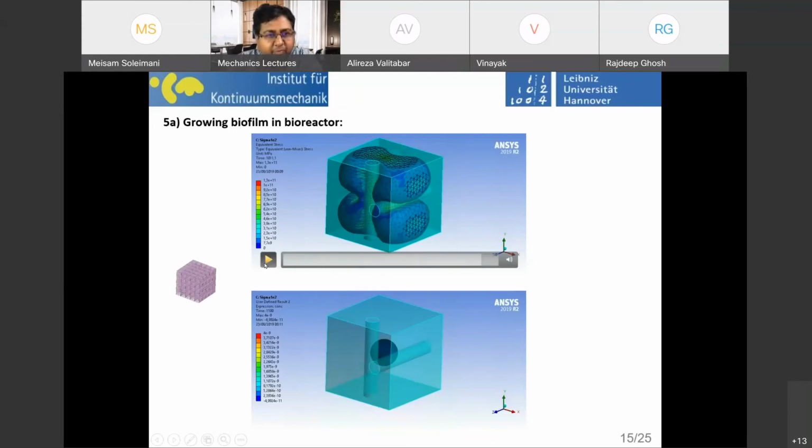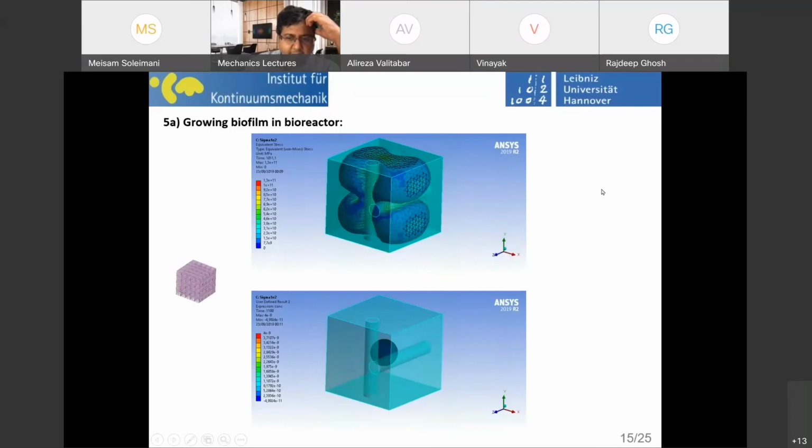If we are talking about constrained growth that intrinsically leads to compressive stresses, it is susceptible to this type of instability or buckling that has to be treated carefully. For example, in ANSYS, I had to activate in some cases line search, in some cases arc length, with particular care.